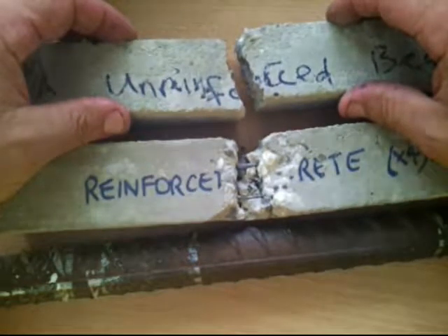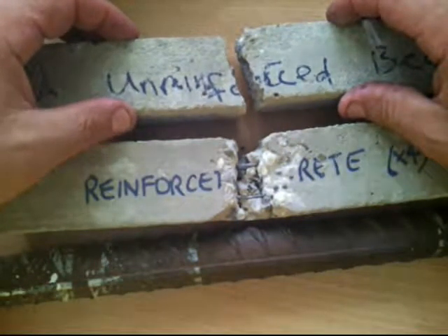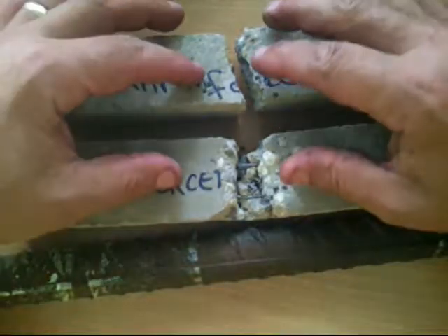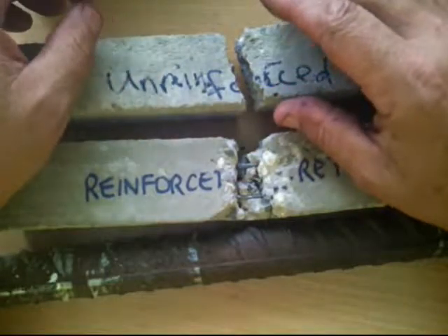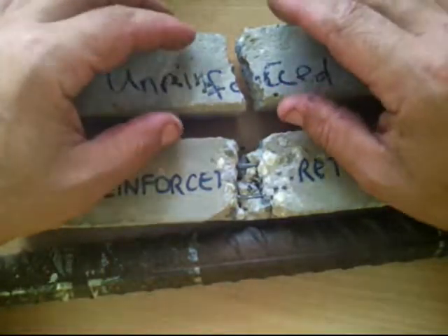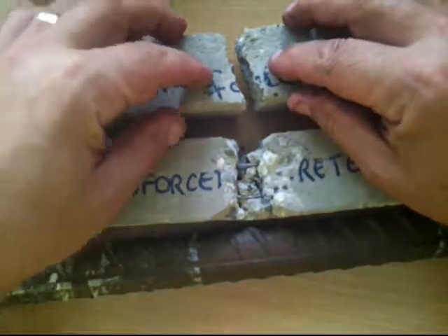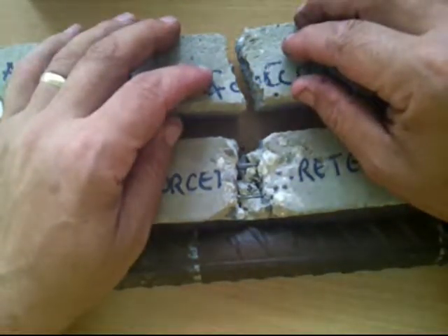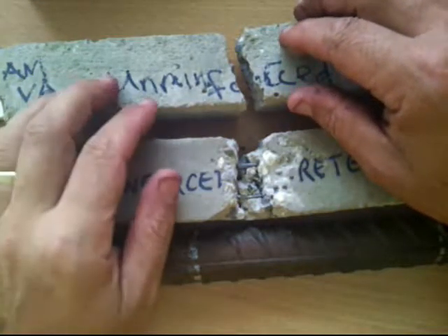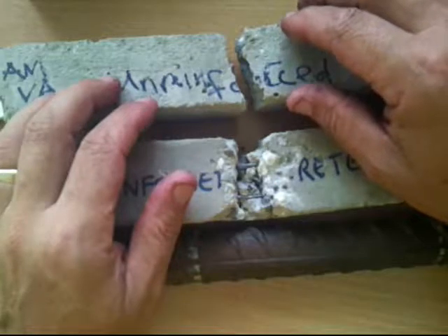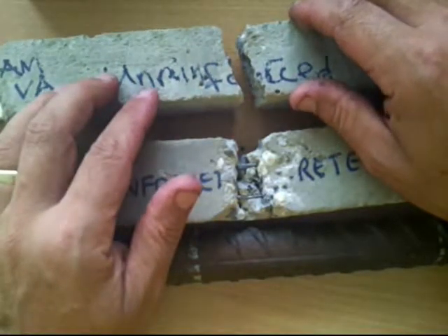Now, a few different things that you need to know. One of them is that concrete beams can be reinforced and created in a lot of different sorts of ways. They can be precast, which means that instead of assembled on site in a building, they can be made into a mould off-site, somewhere else other than the construction site, and then brought in on-site when required and fitted into position. That's called being precast. Especially useful if you want to create lots and lots of the same size shape, and you need them pretty quickly.